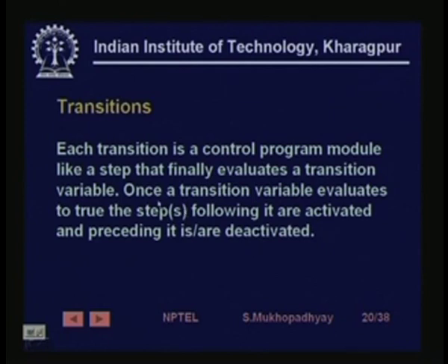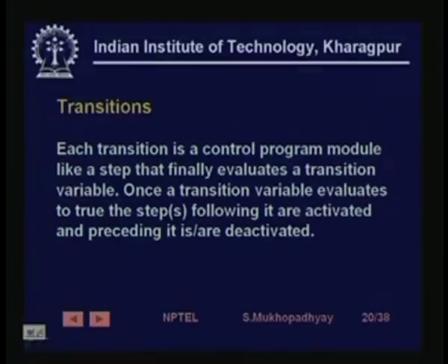And we say steps because in this formalism typically one transition can go to only one step, provided you do not have concurrency. But since SFCs support concurrency, it may happen that after one transition two concurrent threads of execution will start. That is why we have said steps following it are activated, and those preceding it are deactivated.